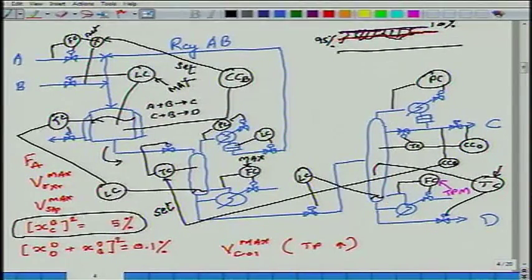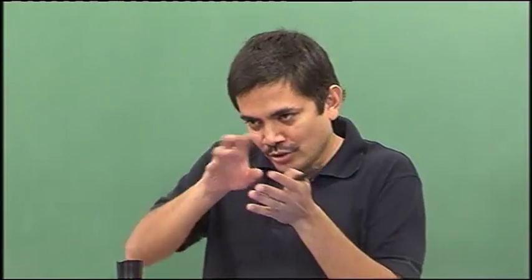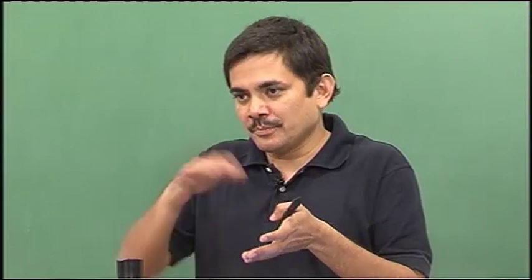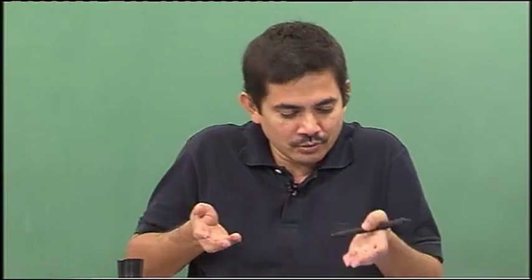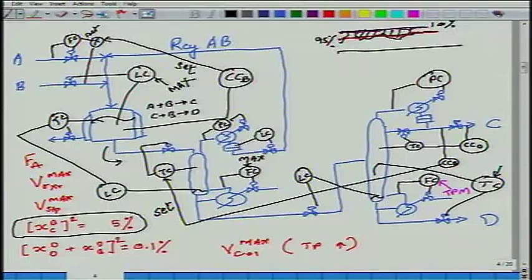More heavy material is coming in because the composition in the reactor has changed because of extra consumption, because the temperature has increased. So more C and D are coming in. Those C and D are designed to go down. As they are going down, the temperature will go up. If the temperature is going up, what will the controller do to the feed? It will say increase the feed.